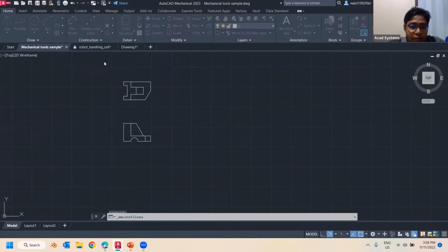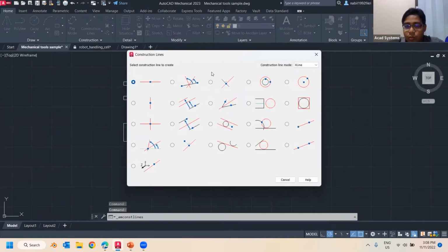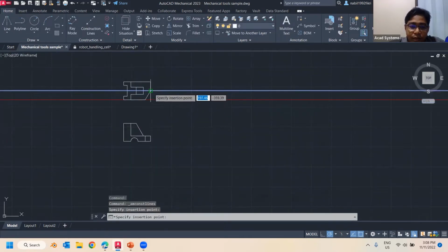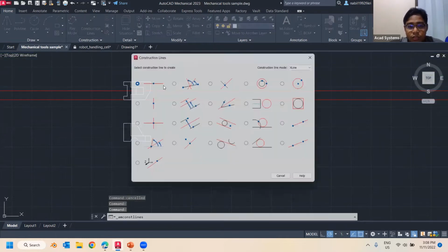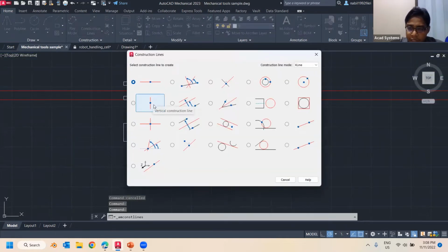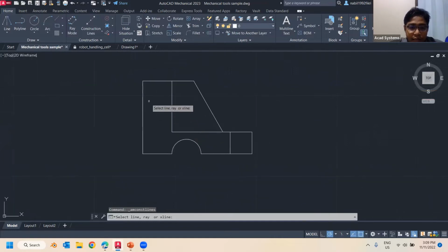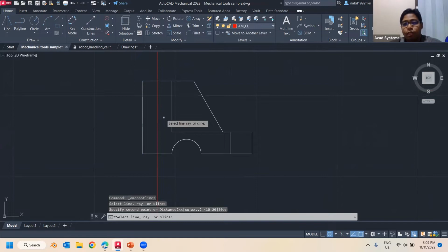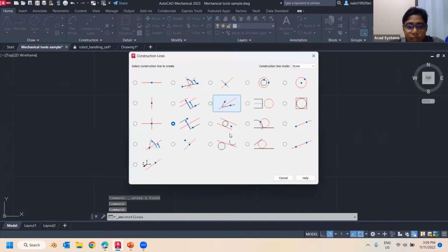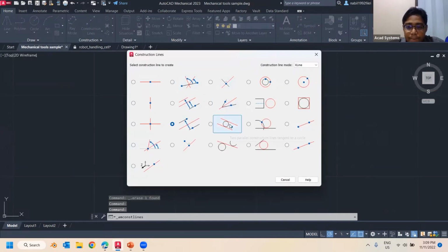Now, if I take a look at construction line over here, once I click, automatically it will show me different things that you can do. Maybe I needed to use for the horizontal constraint. So I can just click. Maybe I need to change, maybe for the verticals or maybe both. Maybe I want to have a half distance, so I can just click for the half distance. Say I click from here until here. They will click the half from that two particular point. So there are several of the construction line that might be saving a lot of time over here.